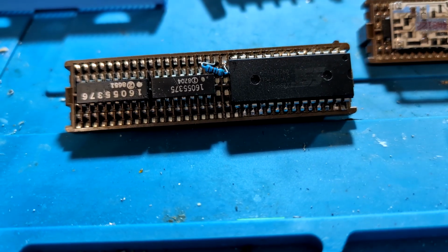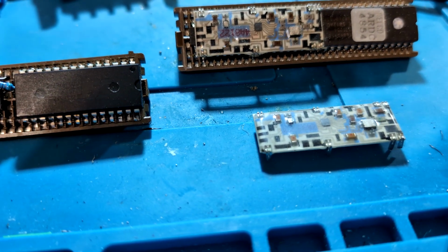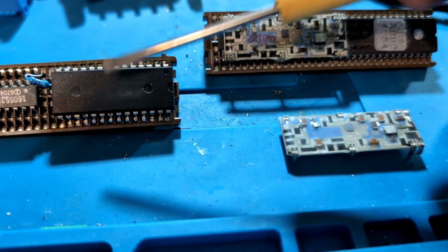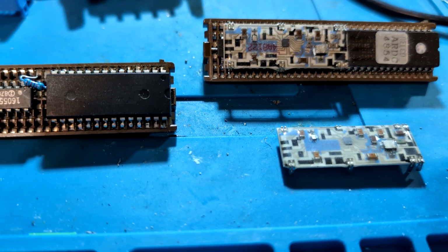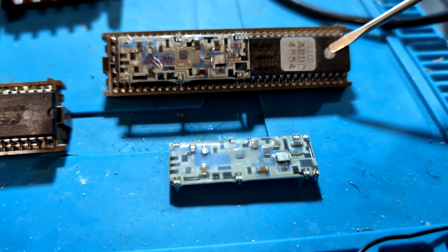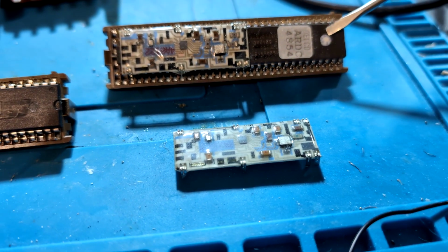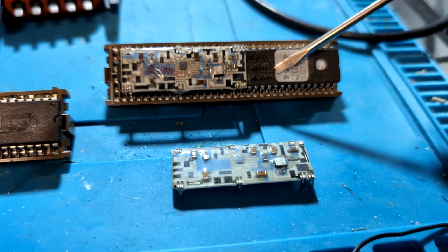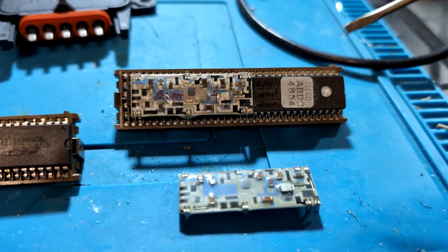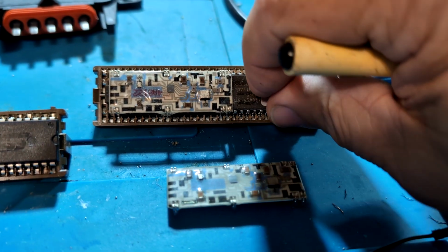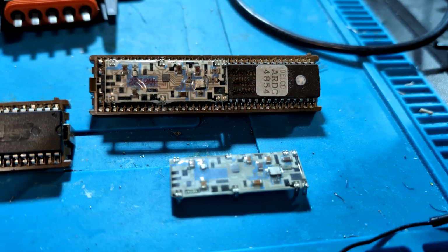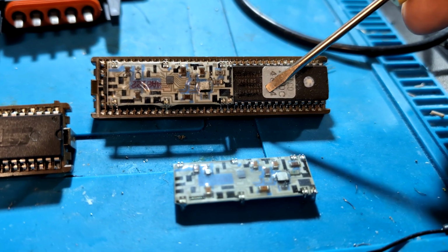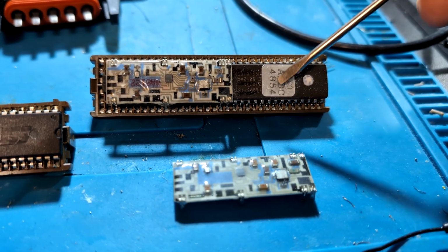EEprom, which is electrically erasable programmable read-only memory, as opposed to an EPROM, which is an erasable programmable read-only memory. The difference between these two is effectively, if you wanted to reflash this with a modified program, it could be done, but it's very cumbersome and time-consuming, because what you have to do is remove this piece of tape. I don't have one removed here, but anyways, if you remove this piece of tape, you'll see actually the chip. It's a clear piece of glass, and underneath is the chip.